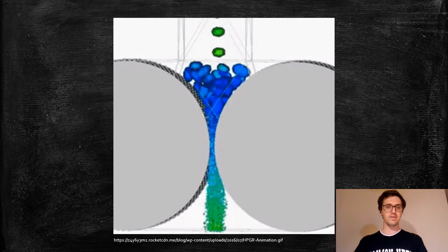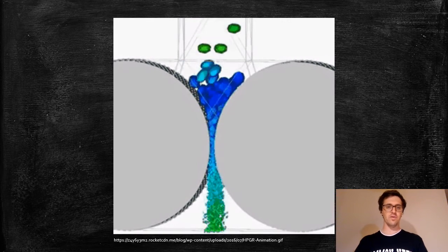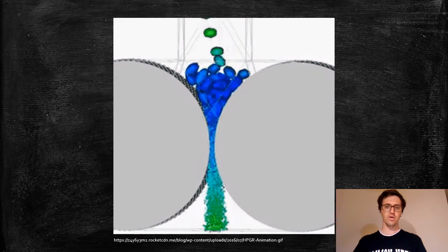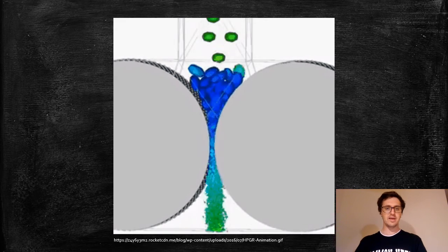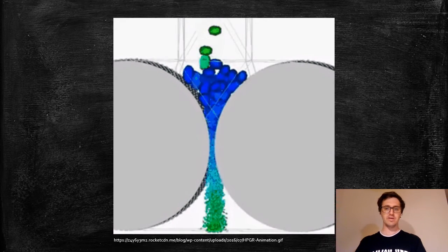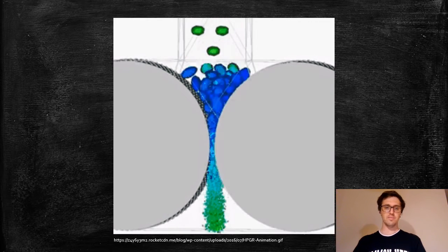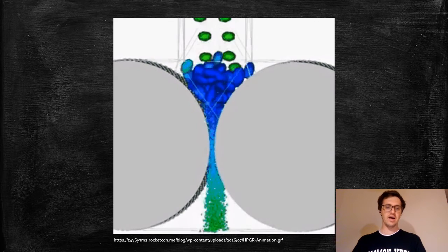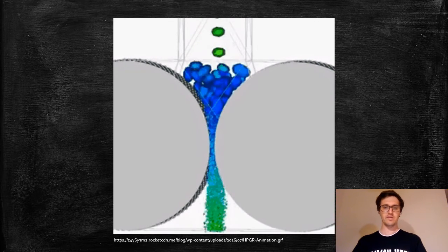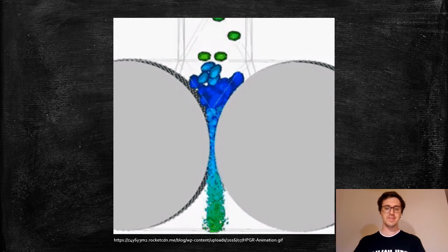High-pressure grinding rollers consist of two counter-rotating rolls. Ore is fed from the hopper through a gap between the two rolls, where it is broken into finer pieces. Their popularity is increasing because of their lower energy consumption, their wearable components last longer, and they are simple to maintain. However, HPGRs are sensitive to material characteristics and the feed rate through the hopper, so fixed feed solutions limit their efficiency.